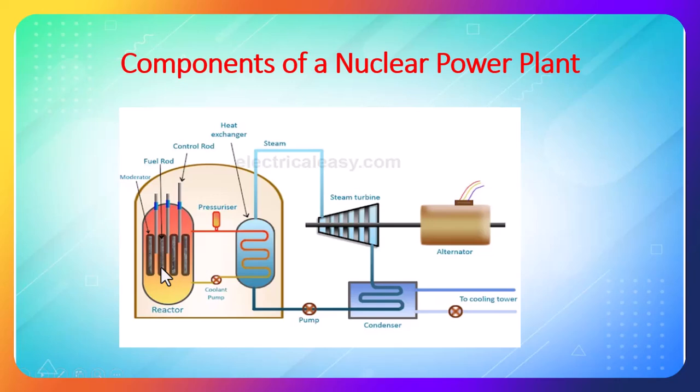See the size of the fuel rod inside your Kalpakkam power plant, we all know it will be as small as a needle, a safety pin needle. So that size is more than sufficient. So that is your fuel rod. Then I will have a moderator, then I will have control rods. When you immerse the control rods, they will absorb the excess neutrons. So you will go on absorbing the excess neutrons, and you will keep the process in a controlled condition. You will not allow it to become uncontrolled.